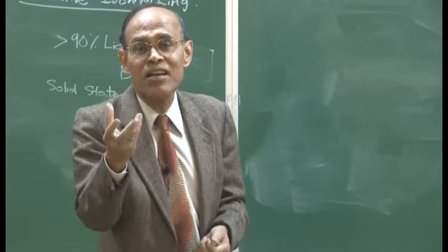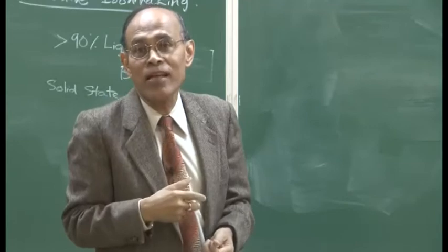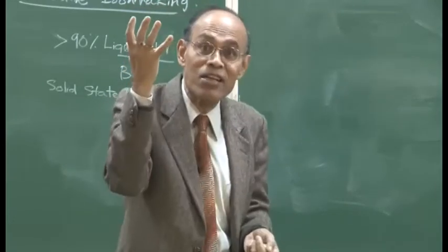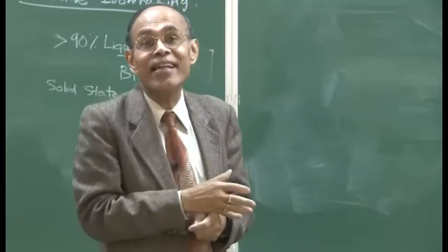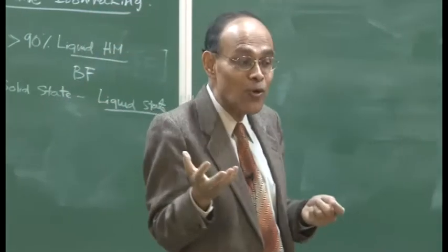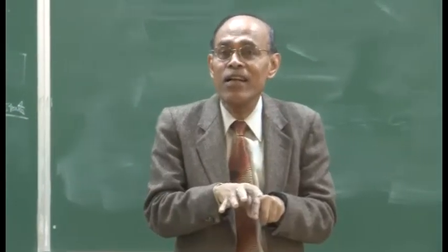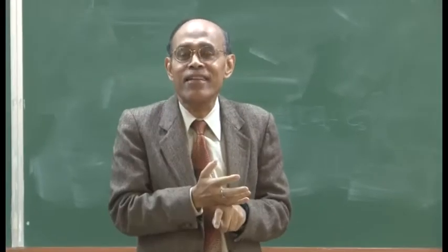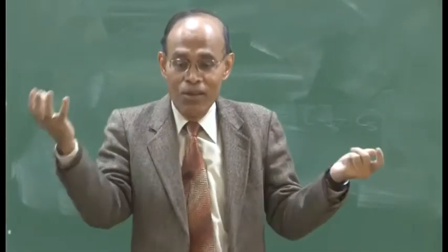And what is that ash? Bulk of it is silica actually, and that is why the blast furnace gets very high silica content, because we are using Indian coke. To contain the silica content so that blast furnace can be operated at a little bit higher temperature, coke blending is done.